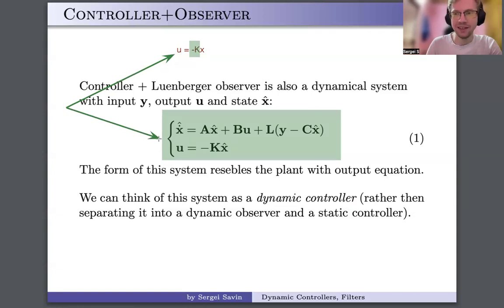And you have to update it. So you have to somehow design integration law. Like this integration law has to be designed. If it was a discrete controller, then update law would be just addition, basically. But since it is a continuous time controller, you have to use some kind of integration scheme. And you have to update it every control loop.